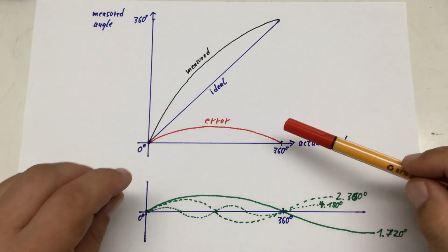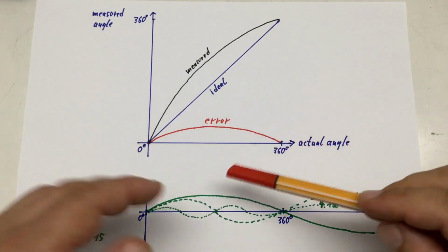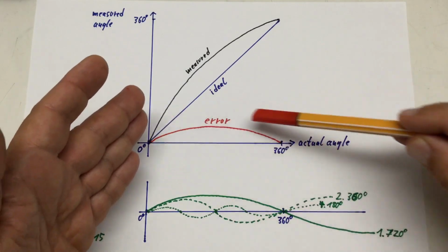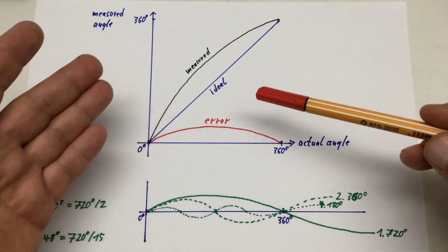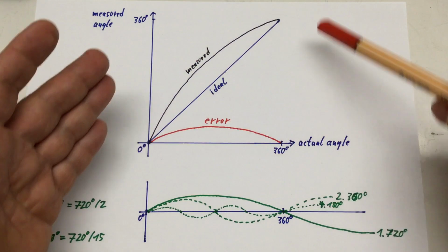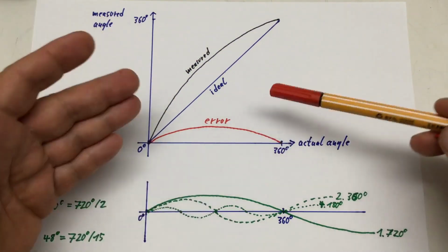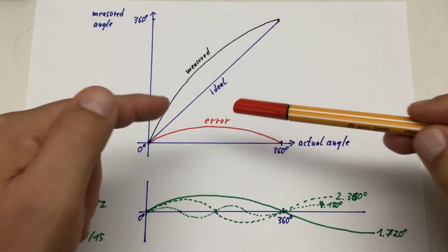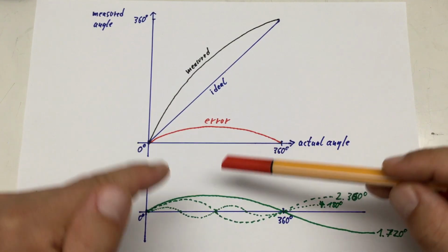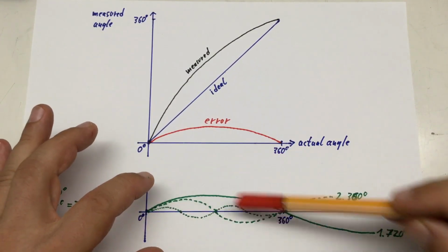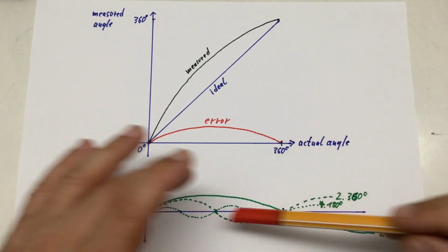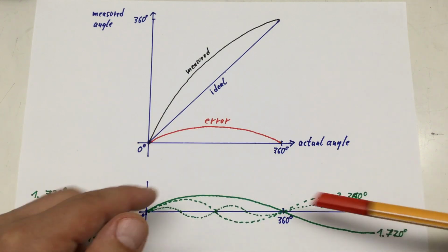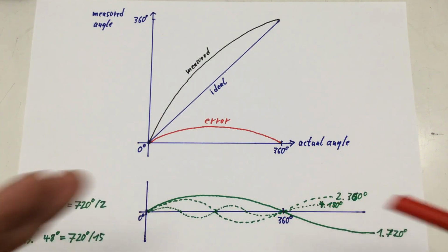And here comes finally the harmonic part. We take our error curve here. We would have, of course, beforehand measured the error with some external devices and use a Fourier transformation to get that into the frequency and phase space of a base frequency with its harmonics.